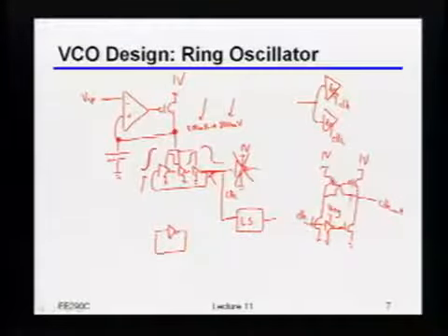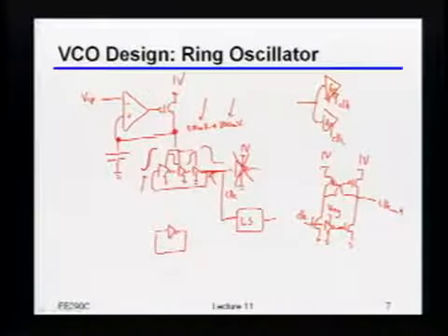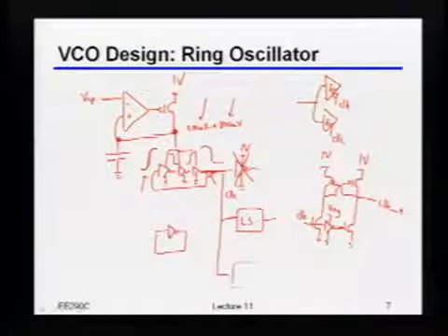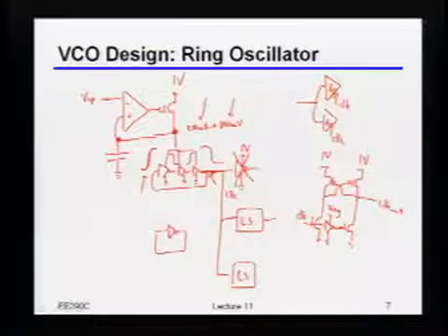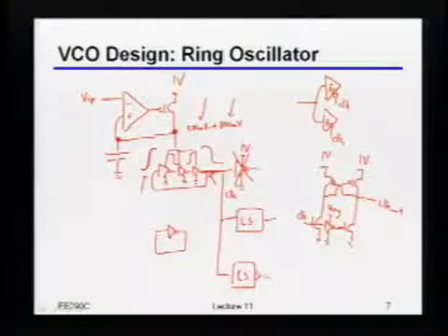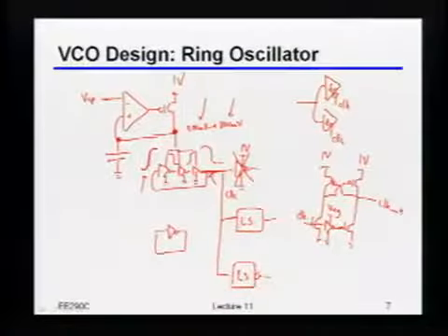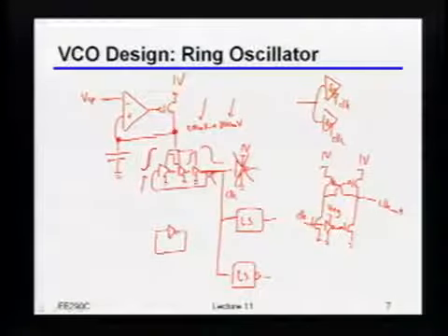If you really wanted to do something like this, what you'd probably have to do is build 2 level shifters, where in one you take the bar output versus the other. Each individual duty cycle would still be wrong, but at least the rising edge to rising edge would be the same. So in general, you have to be careful anytime you do these level shift kind of things.